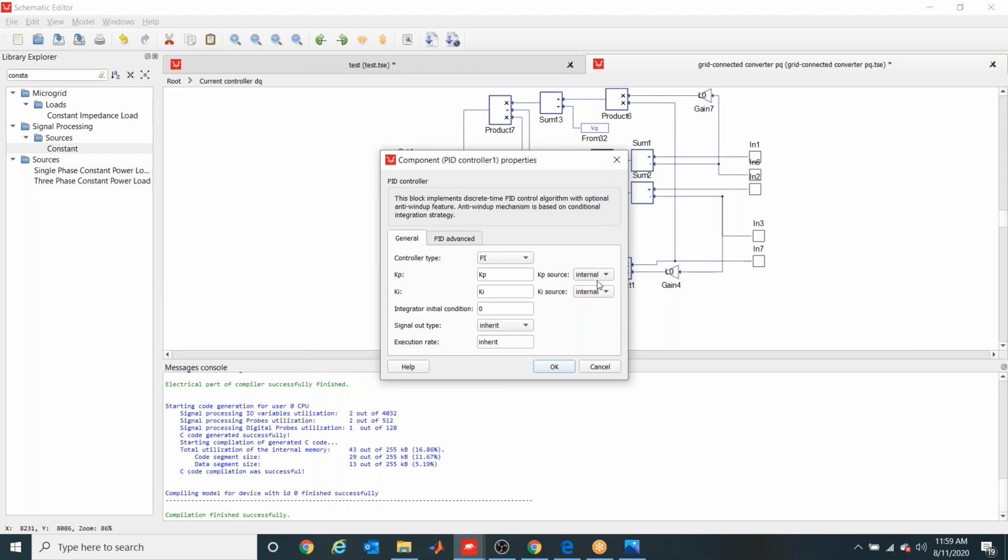No, sir. Actually, my problem is my PI controller is sitting in the DSP, the dSPACE. I'm not using the PI controller of the software. I've built the PI controller in dSPACE and generated the control signal. Can I pass this control signal to the analog pin, or do I have to pass it to a discretized digital pin? You need to give that signal using the analog pin. Using the analog pin, not digital, right? No, analog pin.